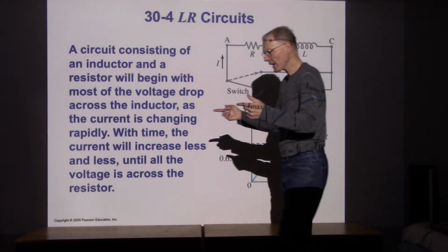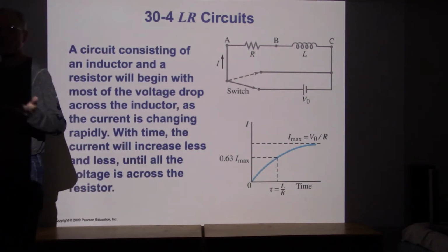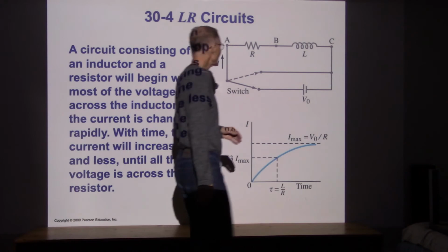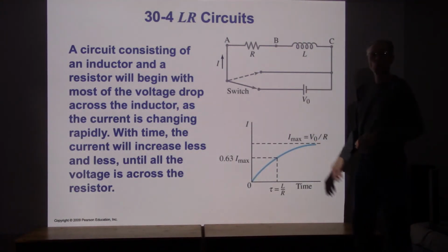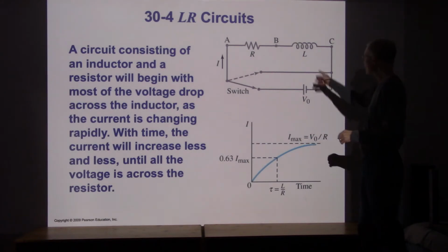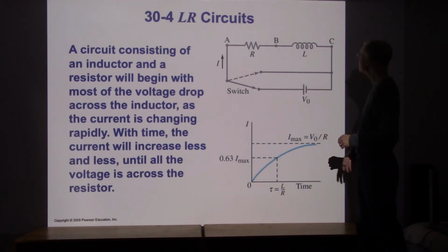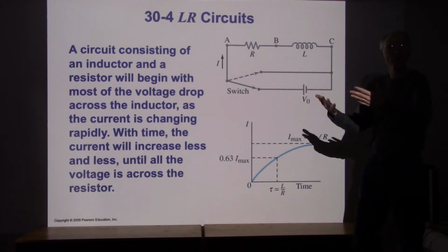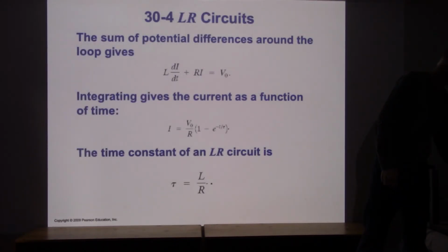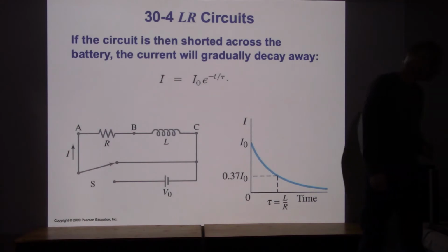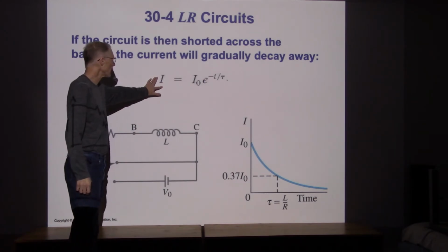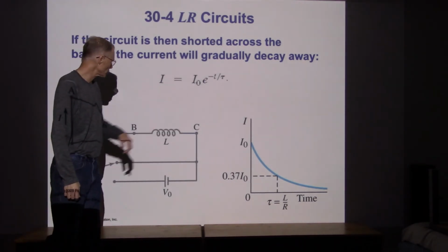When we charged the capacitor and then discharged it, it wasn't that difficult. You could imagine a capacitor charged, just sitting there with nothing connected to it. But you can't really have an inductor just sitting there with current going through it. So we have to contrive a situation where the current never actually stops. So again, we have to switch that very quickly to make sure that the current never stops. Now if we do that, here is the de-energizing formula, and the current will drop off exponentially.